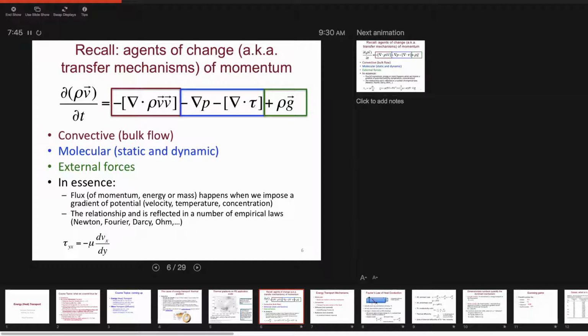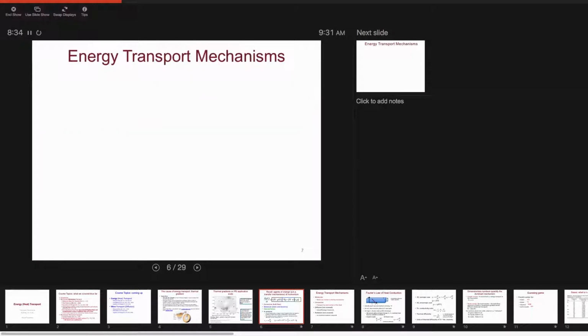So the relationship that we had that was very important to estimate in these stresses is a linear relationship in my shear stresses. That is the simplest one we could have for a Newtonian fluid. Just to recall, in the very simple case, a one-dimensional case, because we were looking at only one velocity transferring across only one of the directions, we had this linear relationship for shear stress. This is my coefficient of proportionality, and these are my gradients that are driving the whole thing. Now, we had to have a tensor because velocity is a vector field. It's going to be a little simpler here.